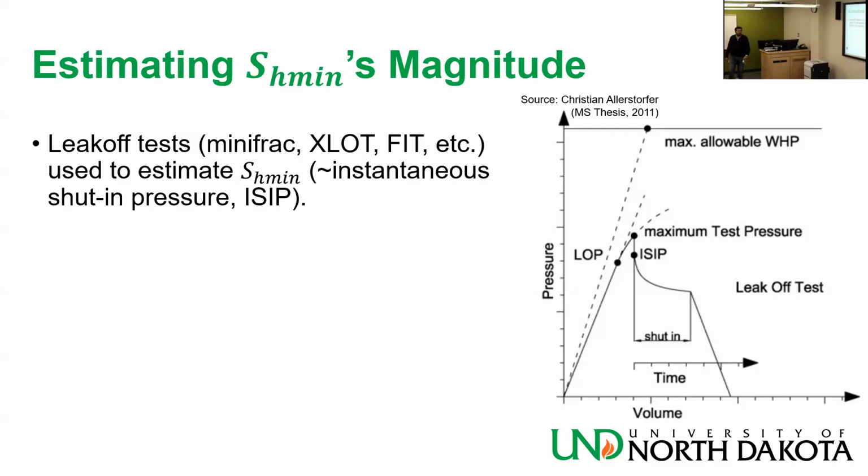It can be confusing when you are doing this test. Now, what is the purpose of this test? The purpose of this test is to see how much pressure the rock can sustain before it breaks. So when we are drilling, we set casing, we cement the casing, and then we are about to drill a new section. So if I drill a new section, what is the location that is most vulnerable to fracturing?